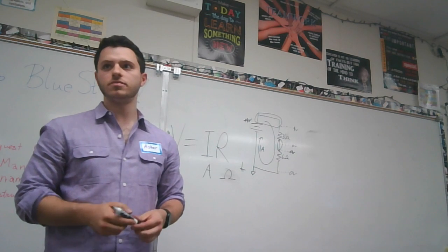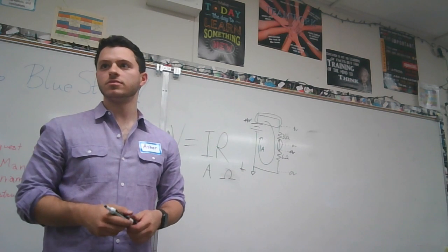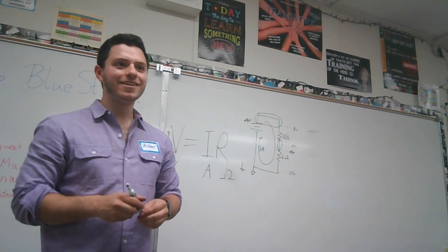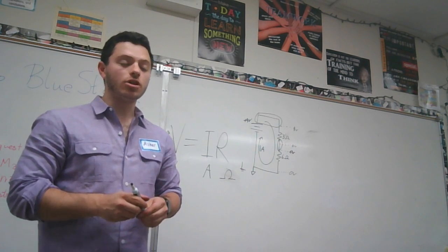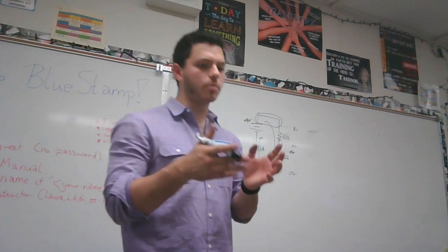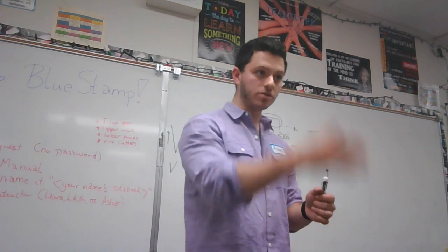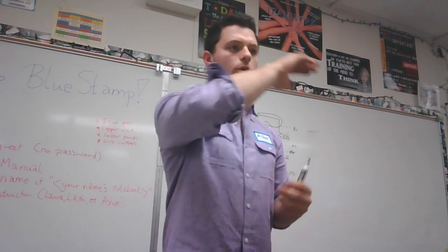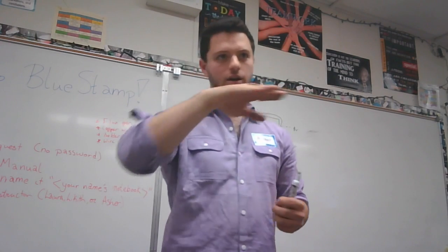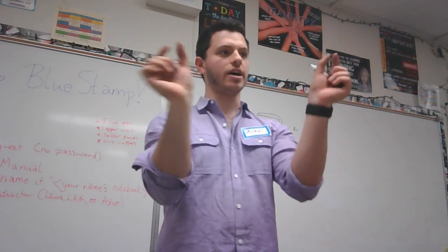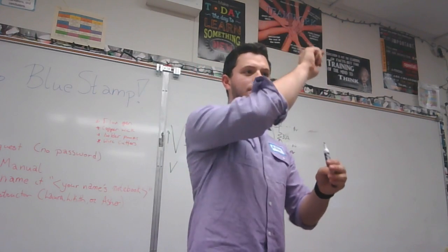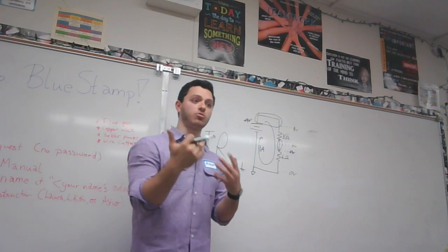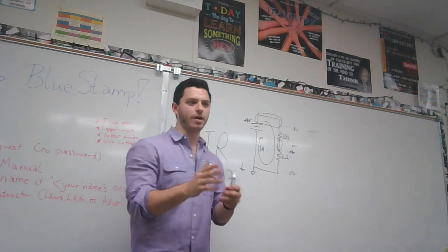Anybody else? You sure? Yeah. I didn't get what you said about the ground thing for a breadboard. Sure. So pretty much with a breadboard, you just have a whole bunch of rails that are connected to each other, right? Most of them are horizontal, as you guys will find out. There are 2 on each side that are vertical. One is labeled negative and one is labeled positive. The one that's labeled negative is usually the one that we use as the ground. So there's nothing special about it on the breadboard.